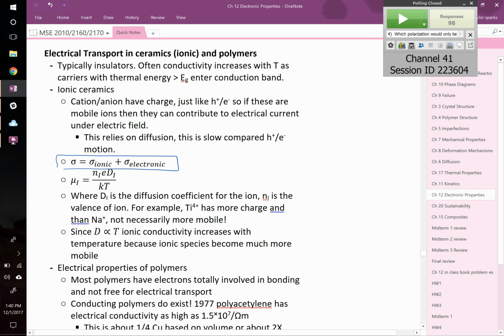And you can have materials that are completely electronic or completely ionic. So examples are like metals, right? Something like iron is going to be almost entirely electronic. Iron ions are able to move, but it's so much smaller than electronic that its contributions can be tiny. And the other way around, you can have materials like the materials used in battery electrolytes, like YSZ. Take YSZ. YSZ, that's yttria-stabilized zirconia. We've already talked about it. That's ZrO2, that you dope some yttrium 3+ on there, and that creates oxygen vacancies.